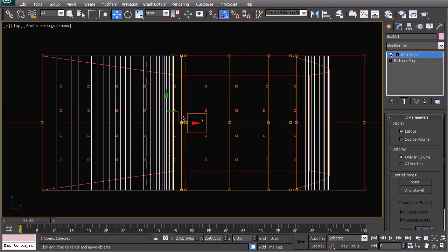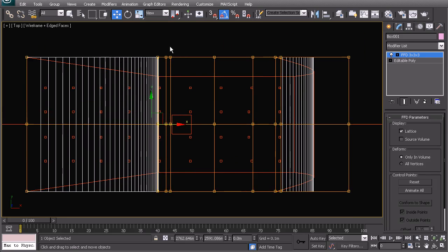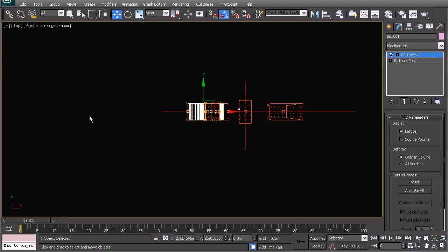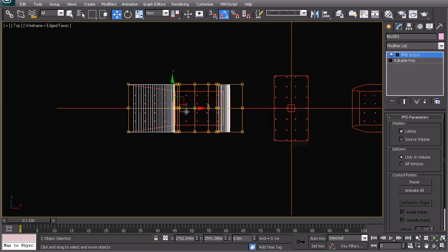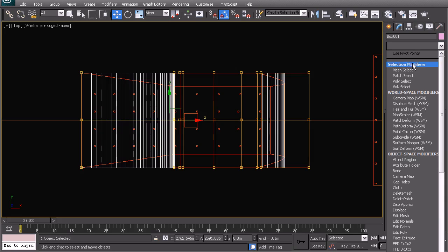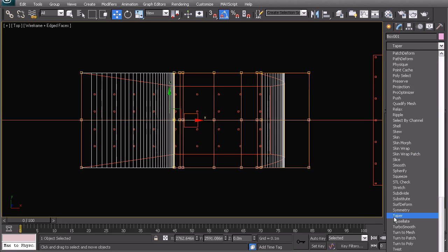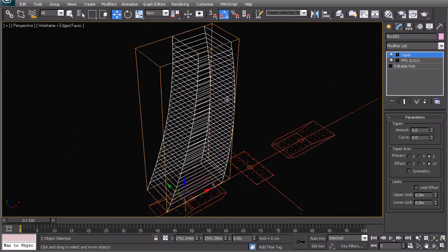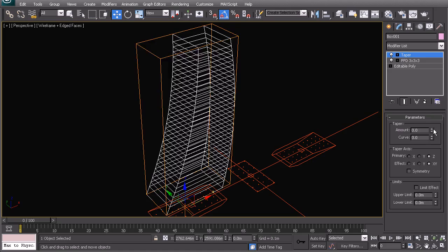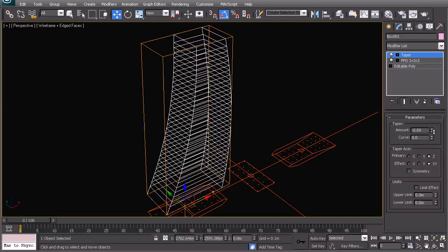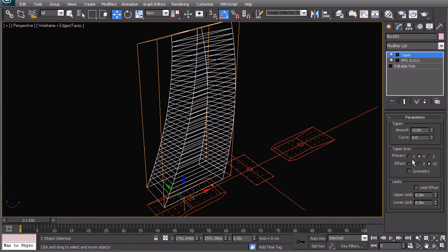We can go into the top view, and we can do the same thing here where we need to taper the building inwards. Now it would help to have an elevation from this side, from the left, so that we could see how to do that. Since we don't, we can just use a plain taper in 3D Max. So we can just write TA for taper, press enter. And in 3D we can start to edit that, but you'll see that it's tapering in all directions, so you want to make sure that you choose the right axis.